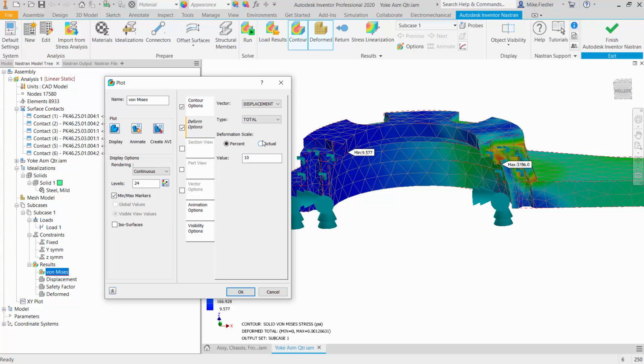And so what I mentioned was, if it looks like that sphere had passed through the cantilever, for instance, it could just be that the displacement on the sphere is much larger than the displacement on the cantilever. So as we exaggerate that 2 times, 3 times, 4 times, the sphere is going to keep looking like it's going a lot further than what the cantilever does. So in those sorts of situations, when there's a gap that gets closed before contact is made, you want to look at the actual displacements in those situations.